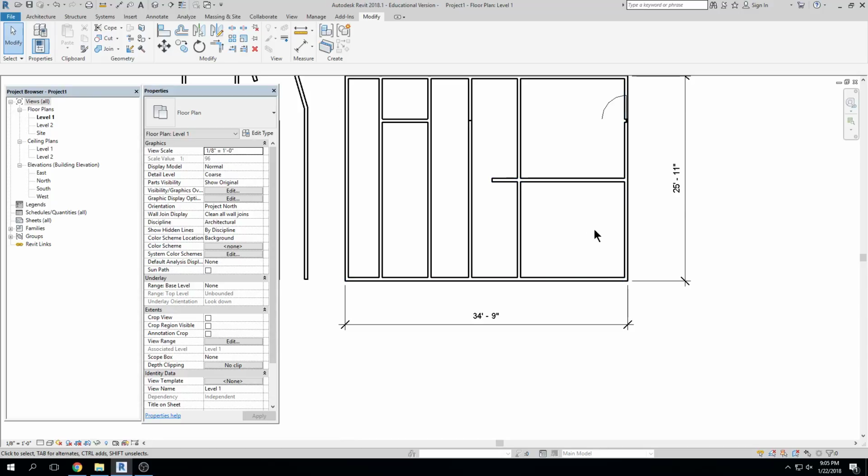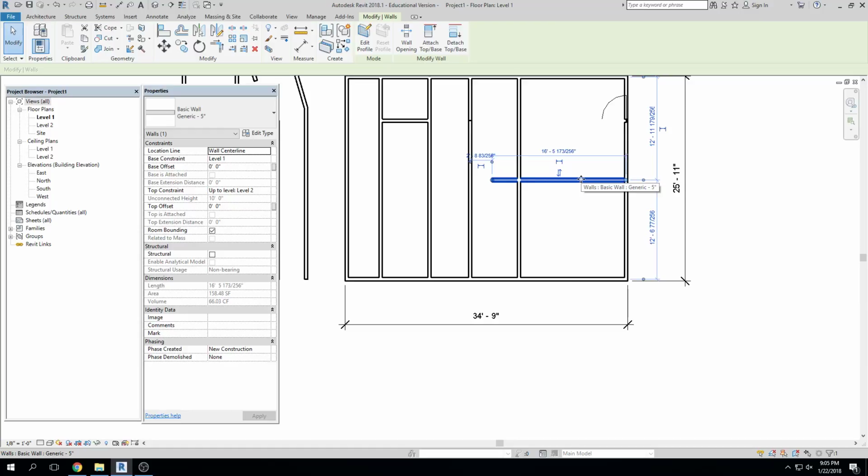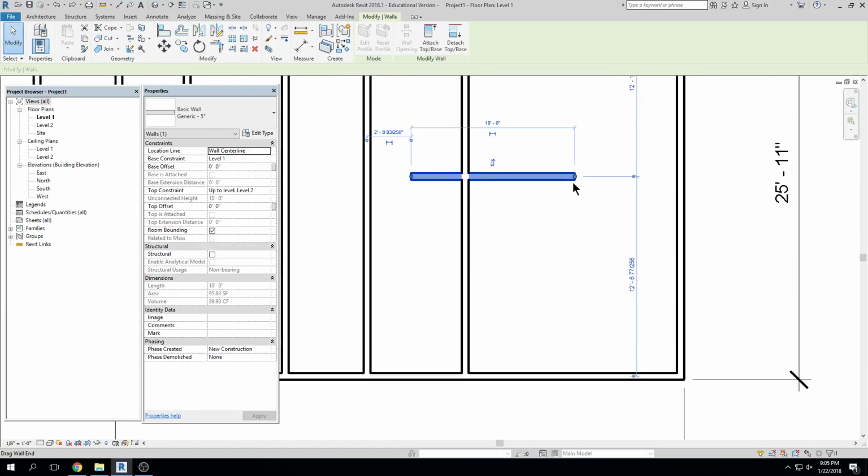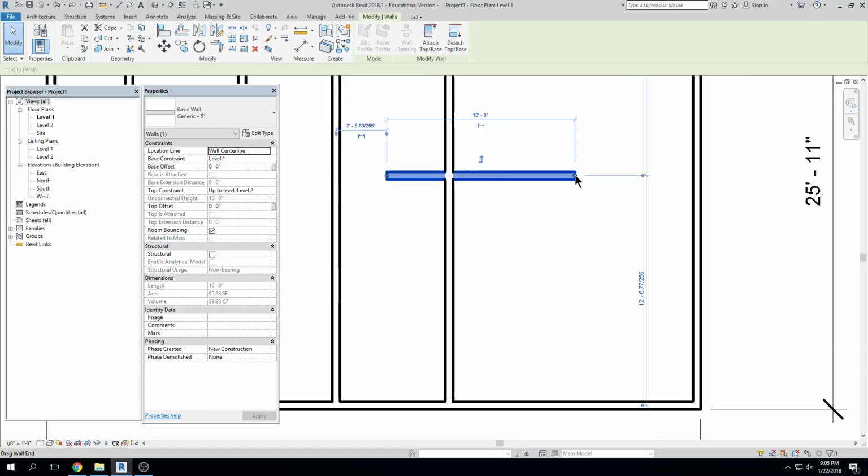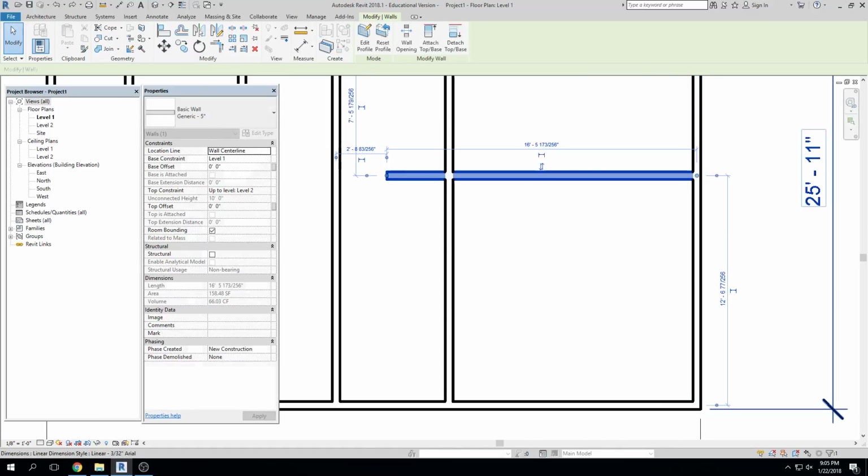But in my mind, you're going to use trim as much as you can. The other thing is, in this case, Revit is really very good about it: you can stretch with the grip very easily and make it straight, right? So I just grab that grip and it joins very nicely with the wall. So I don't ever use those, in fact. But they're there, just in case you need them.